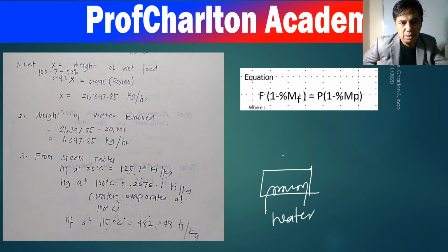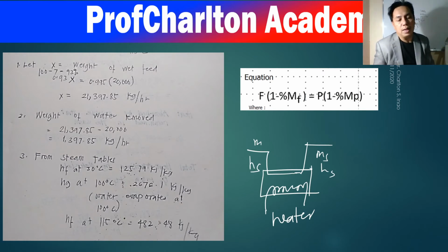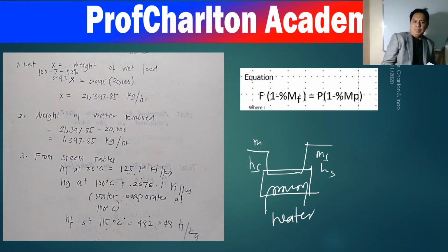It could be steam, right? So there's a mass of steam, then it goes out here. So there's an enthalpy here. So mass of steam, then enthalpy of steam. It's because the heat energy is there as an internal energy in the enthalpy. It can be read in the steam table. And why steam table? Because it's wet steam, right?